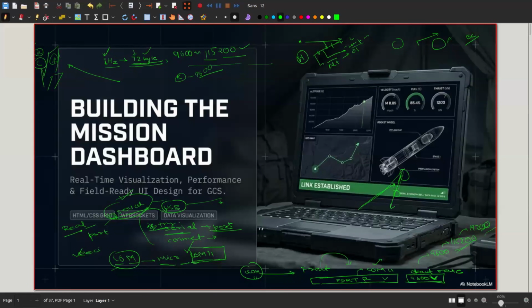Then you select a baud rate, and as soon as you select the baud rate from the drop down, it gets back to your backend, and it says that the user is trying to connect COM11, the port number 11, with this baud rate. So then PySerial assumes, in yesterday's session we discussed that PySerial asks for two values. First is COM, basically the port number which you are trying to connect, the USB port, and second you have to give the value of the baud rate. So you have to give this manually.